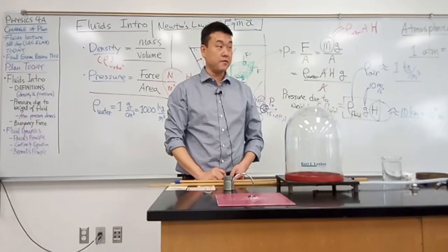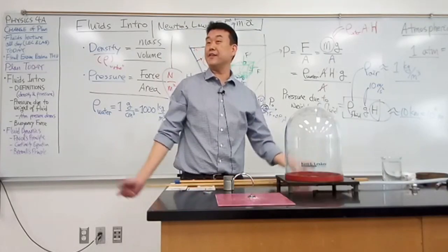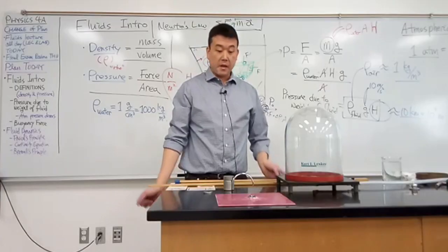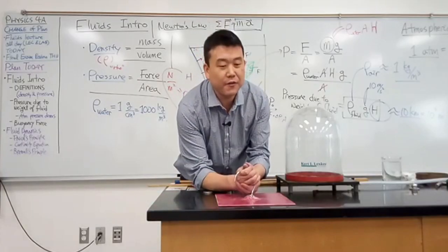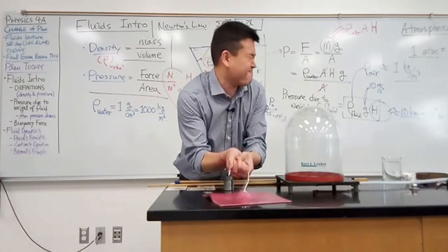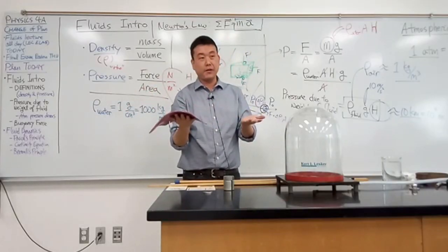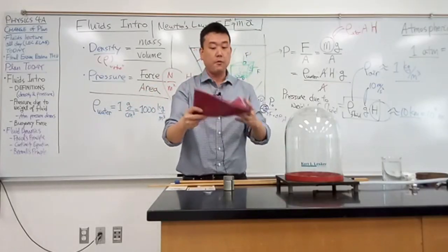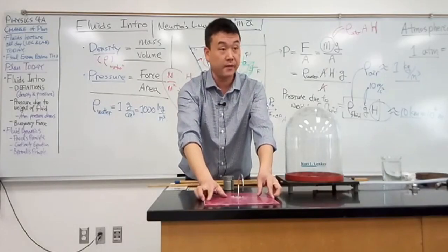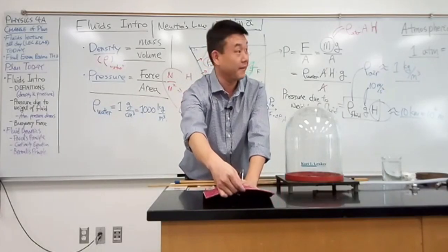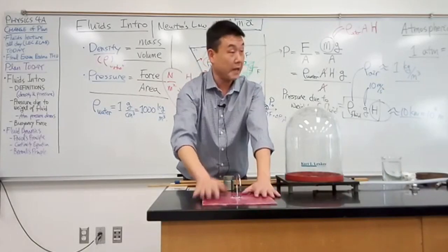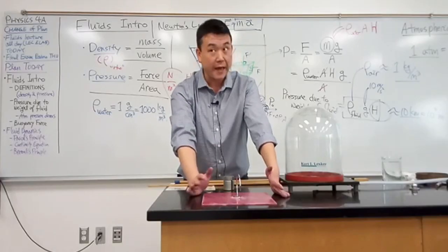It's very large. 5,000 newtons is the weight of a 500 kilogram thing. So if you lift this hard enough, you will actually be able to lift it. And it's not because I can actually lift the 500 kilograms. If you watch it carefully, what happened is that this distorted enough that at some point it let air in. But yeah, atmospheric pressure is that much.